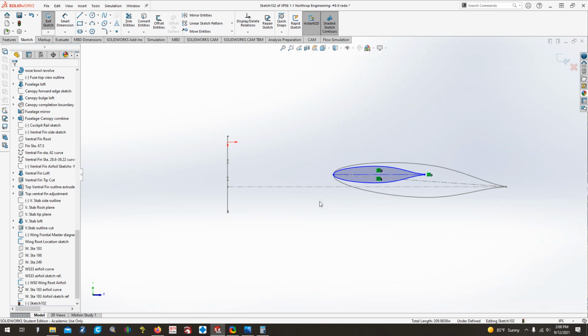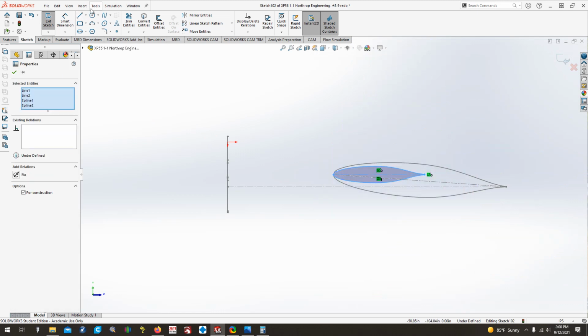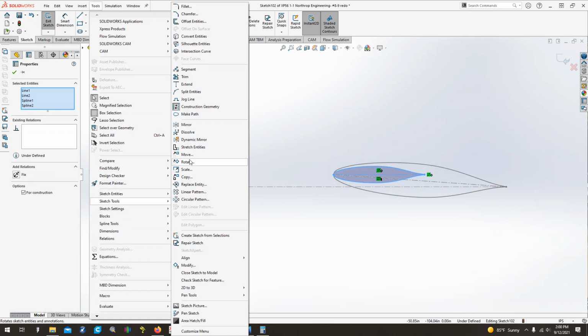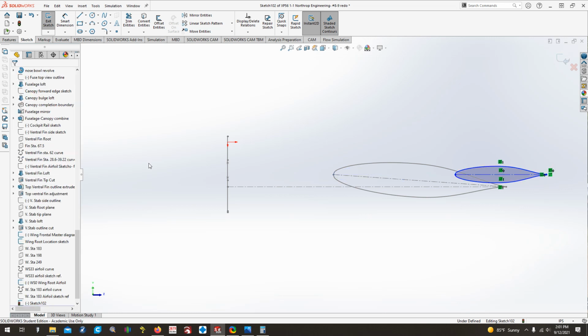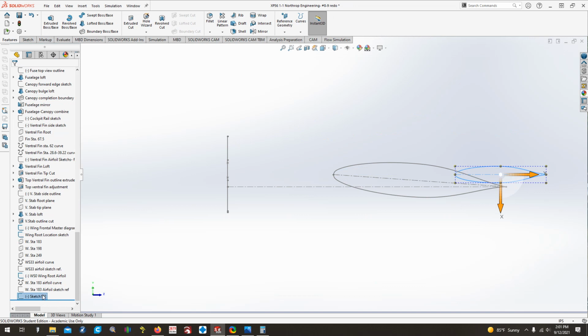Zoom back out. Perfect. Now we'll drag it, select it all. Tools, Sketch Tools, move again. And we'll do from that 91.618. We'll see if it moves it. Nope, it's the wrong direction. Delete that. Then 91.618. And boom, there we go. Now it moves it back, and we can hit green check mark. We can exit it. And then we can save it once again.